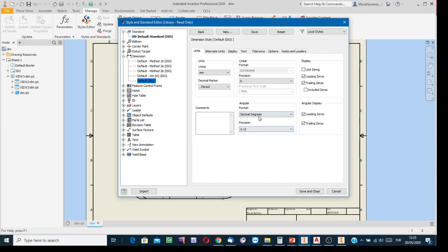For angles, yes, we use decimal degrees, so it is correct. Precision: for the angles, if the deviations use just tenths of degrees, we need to show the nominal value of the angle as an integer. So select the 0 figure option for the decimal part of angles.